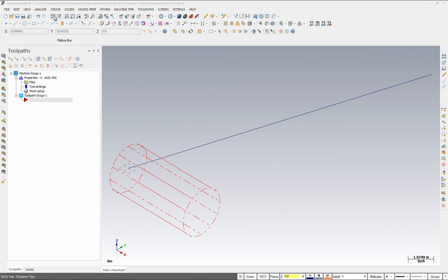The toolpath replaces the x or y axis with a rotary axis known as a-axis or b-axis. Using this option, the part will be rotated about the rotating axis while the tool moves perpendicular to the axis of rotation. The rotary diameter sets the size of the cylinder that the toolpath is rotating about. It is used mainly for toolpathing on cylinders. To machine the helix, you will use a contour toolpath with no cutter compensation.